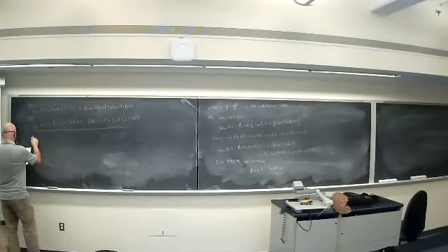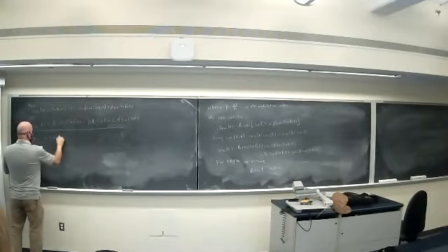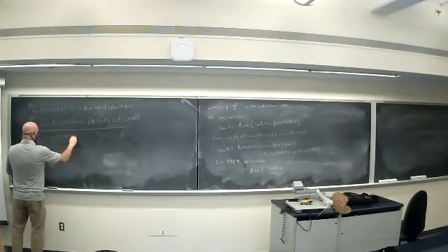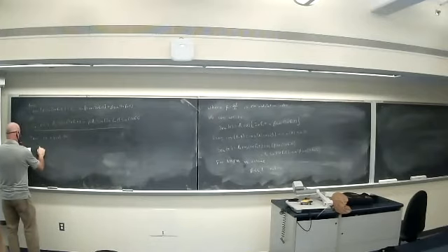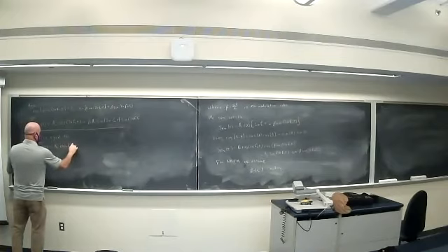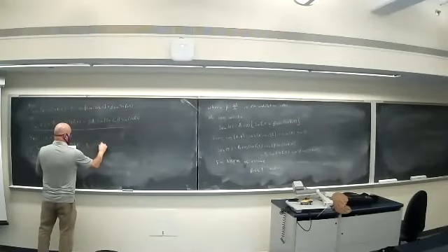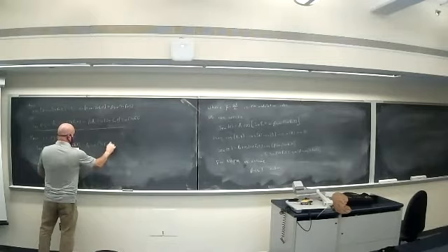So we'll come back and talk about that in just a second, but let me talk about how to actually generate this first. This is equal to, so now I'm going to go back and substitute in my message. It's Ac cosine of 2 pi fc t minus Ac sine of 2 pi fc t.